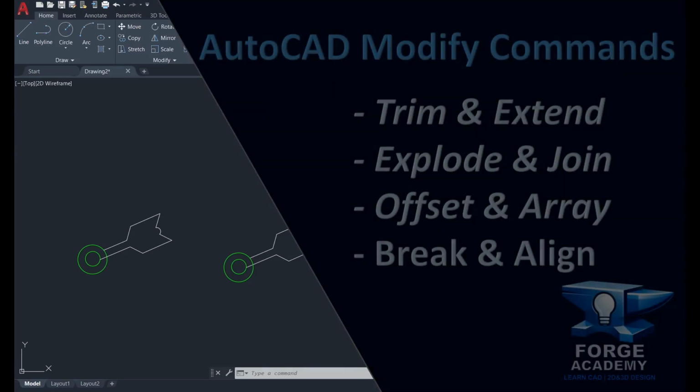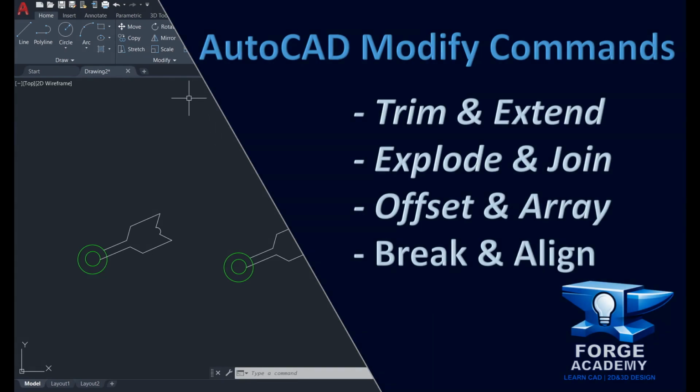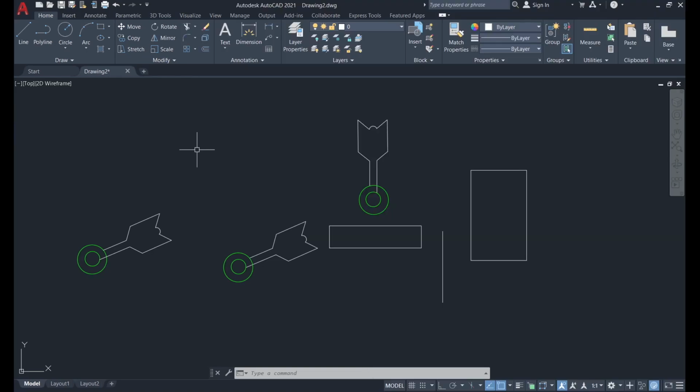Today we are going through the second part from modify panel commands. We are going to take it one by one from trim, extend, explode, offset, array, also break by point, align, and a very powerful command that you want to save for later because it will save you a lot of time. That one is called the polyline edit, but it has multiple options. So let's begin our tutorial today with our latest drawing from the previous tutorial.